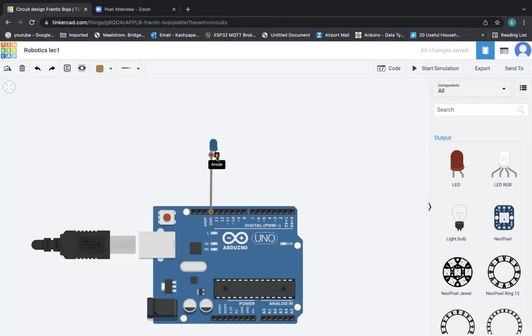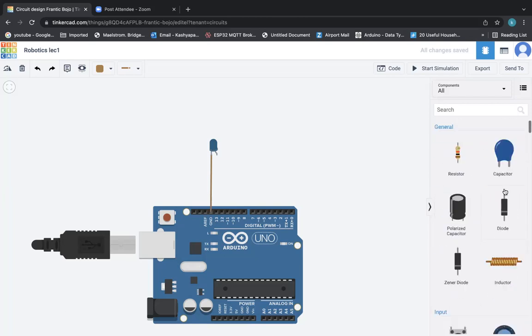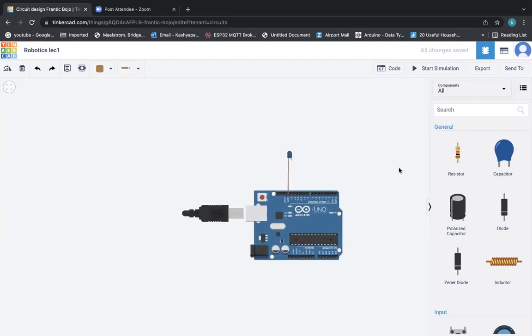Here you can see this red box, which means I have selected the pin, right? And when you select this also, you can see I have selected the pin. So make sure that you get this red color box, otherwise it won't successfully connect, right? So I have connected the ground pin, and then there's a small thing with LEDs, okay?